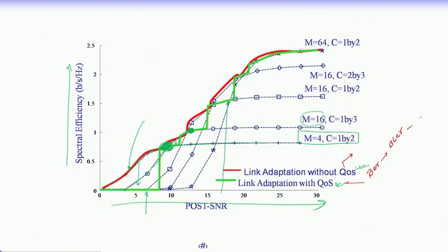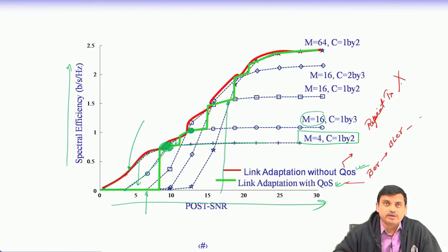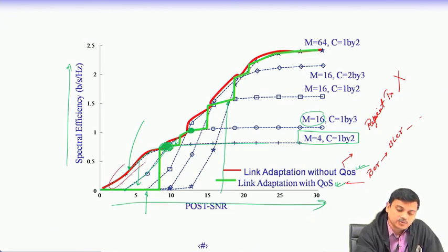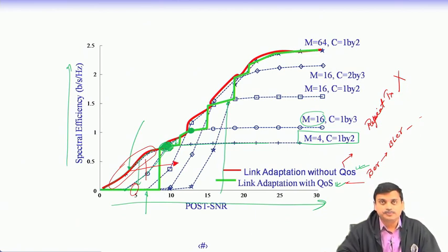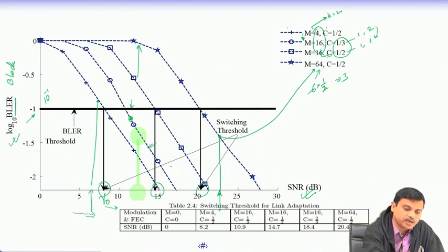Okay. So, these curves are without any throughput computation considering repeat transmission. Repeat TX is not taken into account. So, if we take repeated transmission into account, these lines which appear to be higher than these green lines are going to be even worse. They will shift to the right, because when you repeat transmission, the spectral efficiency loss is huge. So, to avoid that, some prior link threshold is prepared, and that is through this BLER threshold.